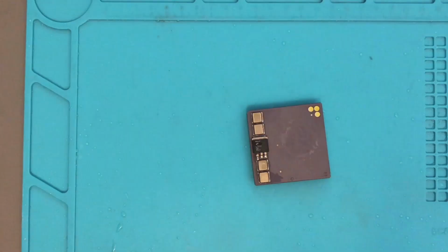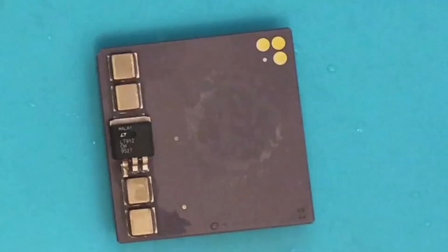So now that we have removed the stock cooler, of course we have the problem with the CPU multiplier, and this now is the first mod. So let's focus on these 3 points here. The first one is the 5 volt supply, the second one is ground, and the third one comes from the fan. Now the interesting thing is that I used an oscilloscope here to check the signal, and there is no frequency here, nothing, just DC.